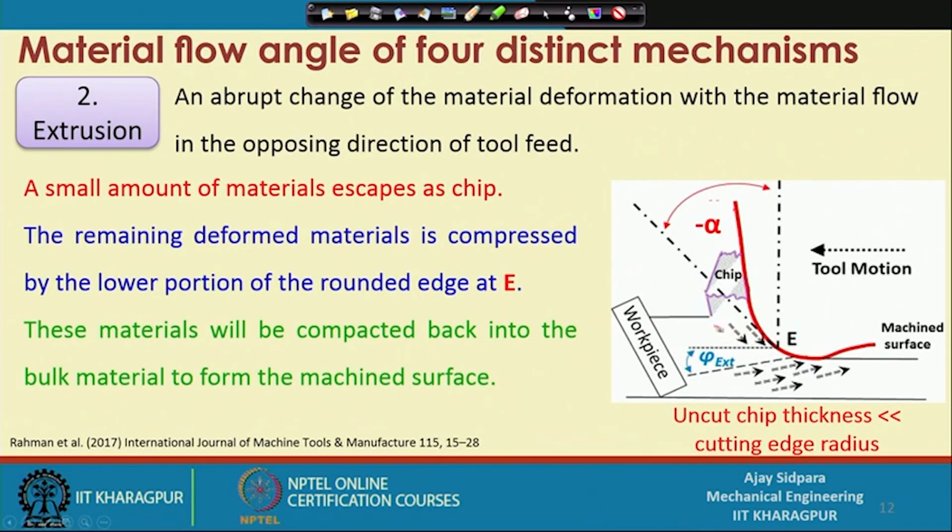So, now whatever is part of this particular thing, this will go in this direction and this will go in this direction. Now, it will be compacted further. So, here it will be a very compressed situation. In this case the top surface property may also get changed. If you do not intend to change the property, then this phenomenon is also not advisable for the micro machining operation.